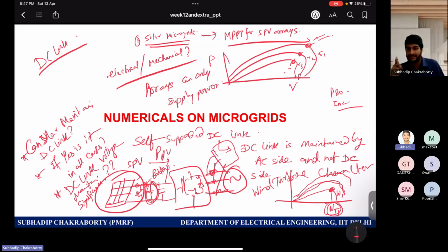Because for AC machines, whether operating as a generator or motor, it rotates in the same direction. In DC, it is opposite. In DC machines, if it is operating as a generator and rotates anti-clockwise, then operating as a motor it will rotate in the opposite direction. But for AC machines, this is not true. For an AC machine, the direction of rotation as generator or motor is the same.